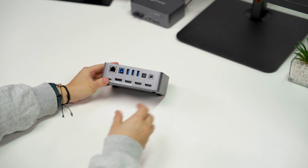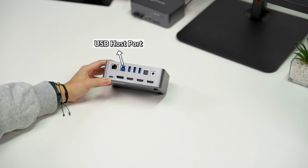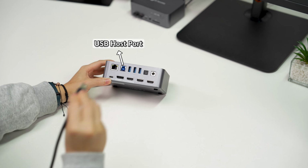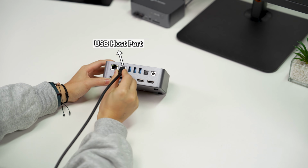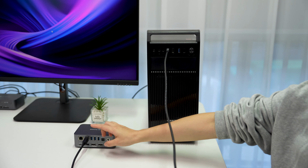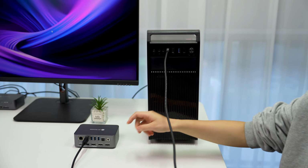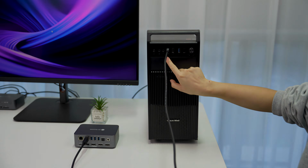If you are using an HDMI or DisplayPort KVM switch, you will see for each source device, there are not only ports for video input, but also a USB host port to connect to your PC. If you skip this, even though you have connected your USB devices to the KVM switch, they are not connected to your PC at all.